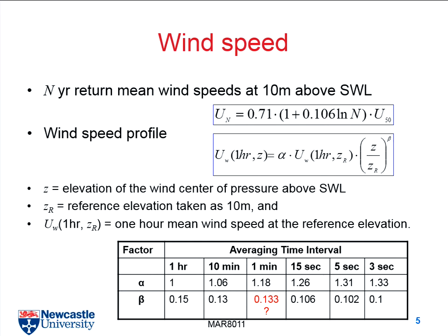So, like I just said, sometimes we assume that the wind speed is for a 100-year return period, but sometimes it's for 50 years, 200 years, or 500 years. For 50 years, usually it's from the data, because for different areas, we always have some records for the wind speed.